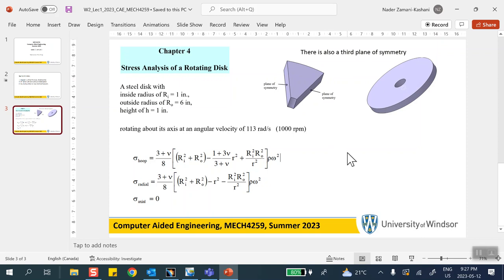Isn't that exactly what we mean by a roller condition on that face, or a surface slider on that face? The answer is yes. Another way of stating that is that any point on this rectangular face does not move in the direction perpendicular to that face. Think about it. That's the same thing as saying that things on that face are basically rollers.